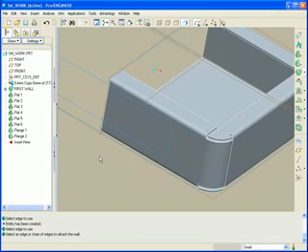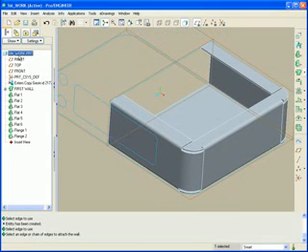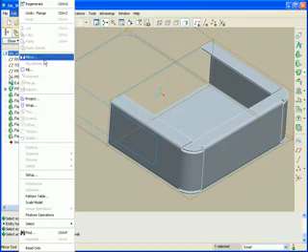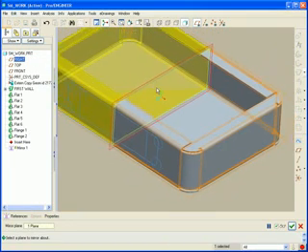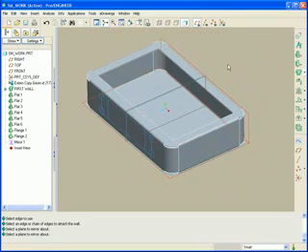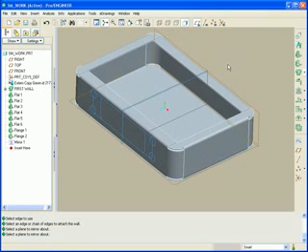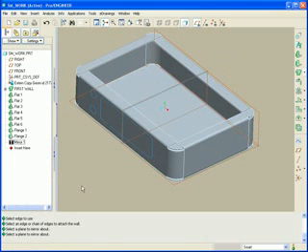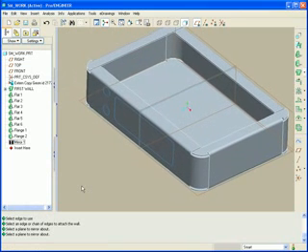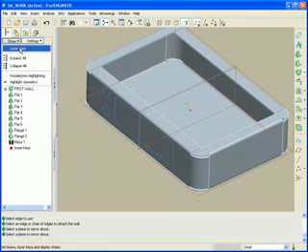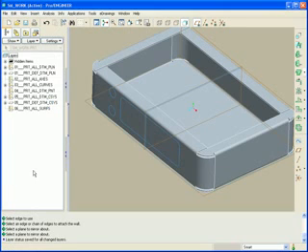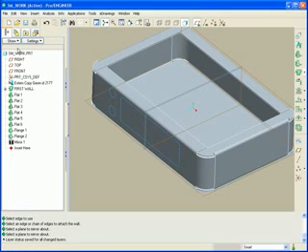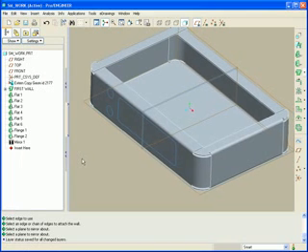Now, if we want to mirror this to the other side, the way that works is you pick the top of the model tree, edit, and mirror, picking then the middle plane. Middle mouse, and that gives you a very nice mirror geometry without a whole lot of references. Now it's important though that you take this mirror feature and you hide it, because it includes all datums and curves and everything else inside there. So you want to hide that, and if you want to make it stay hidden, go to your layer tree, save status.